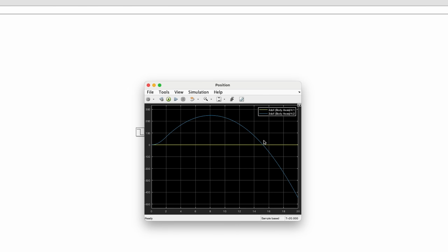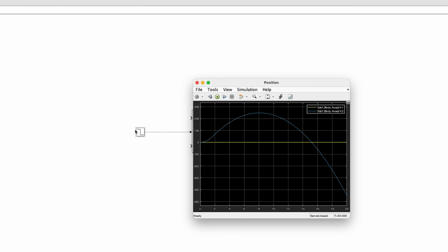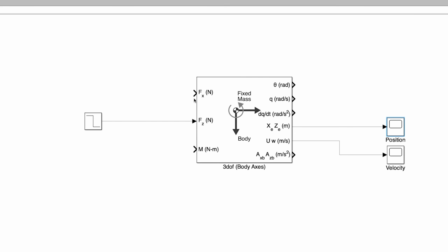Yep, and we hit the ground, and this isn't modeling that it stops at the ground, so it just keeps falling straight through the crust of the Earth. So this is actually the right behavior under thrust. We've now modeled the thrust of a rocket engine. There's more complicated models than just a step function. This is assuming that the motor thrust is constant when it's under burn, and then as soon as it stops burning, it goes to 0, which turns out is actually not a terrible way to model it.